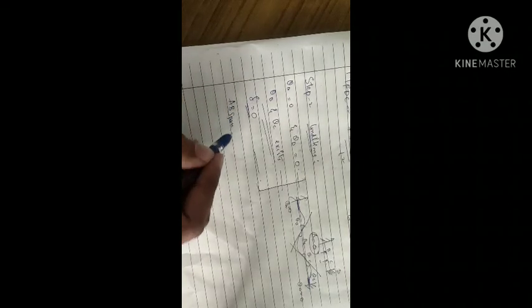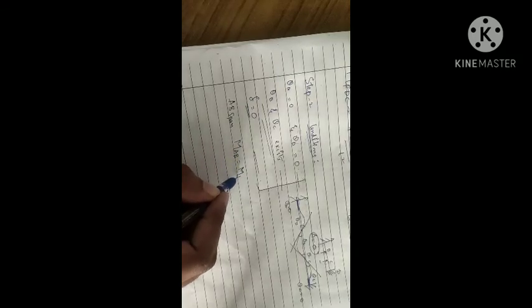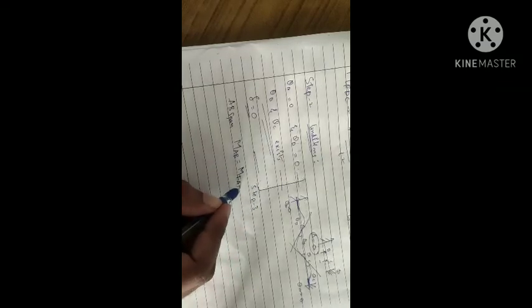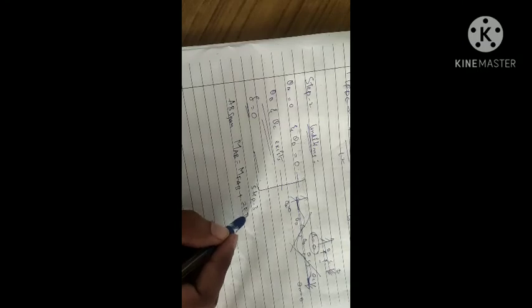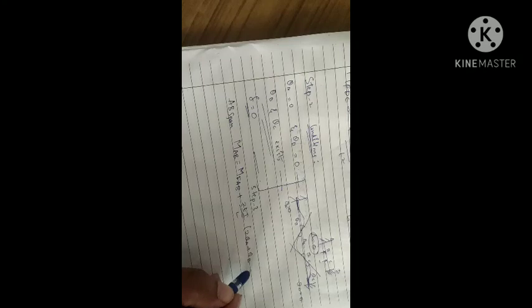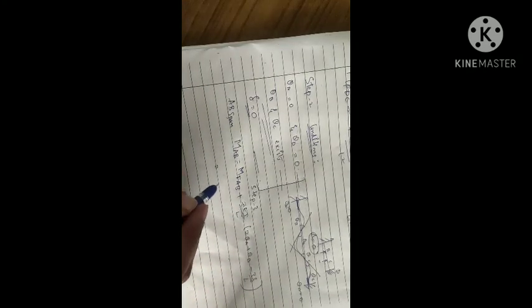So when you are using the slope deflection equation, we will start with the AB span. I have told you what the slope deflection equation is. For AB span, step 3: MAB is equal to MFAB plus 2EI by length, 2 theta A plus theta B minus 3 delta by L. MFAB we have calculated.